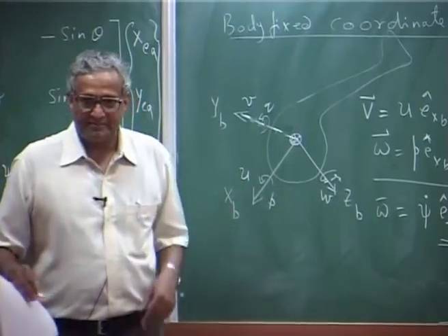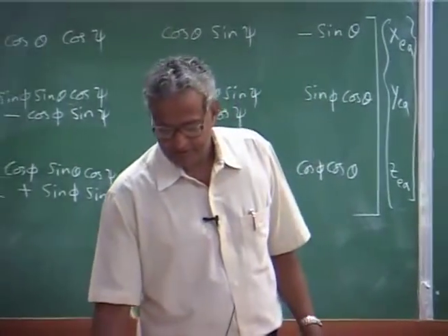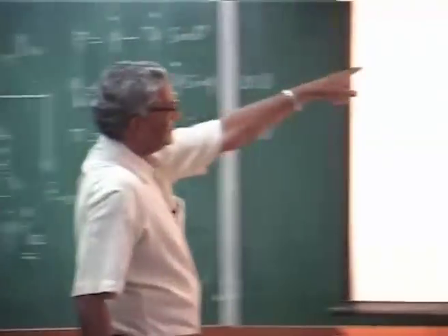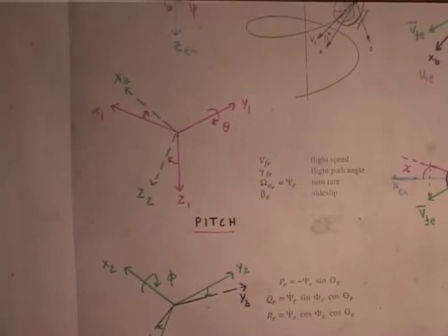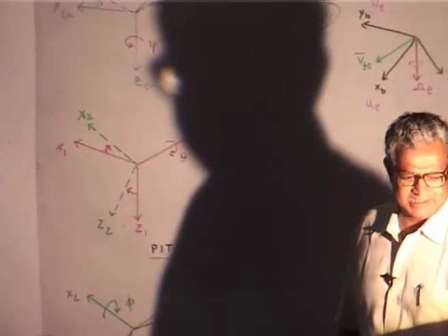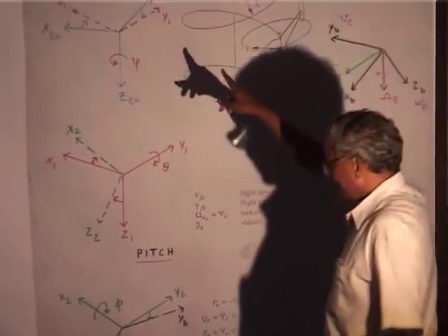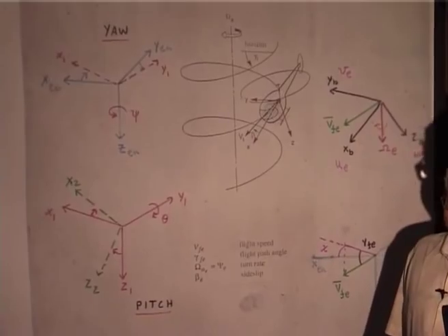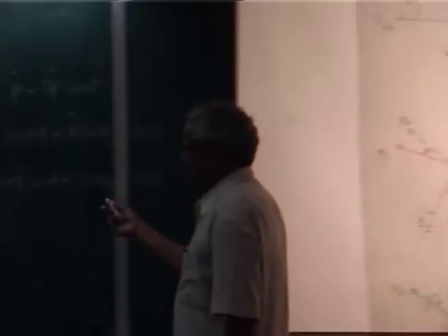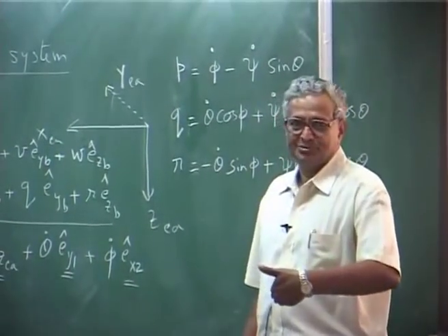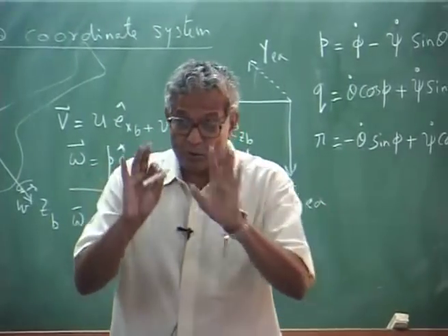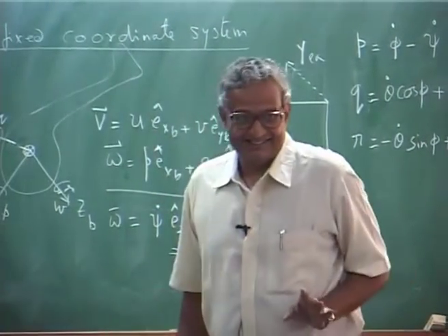Now, if I want, yeah. Again, like the theta, phi and psi. Yes. Now they are with respect to what point? As you have defined here. Okay. That is why that sequence, what sequence you follow, is the most important thing. This is the sequence we are following. Suppose if you change the sequence, you will find a different thing. Usually that is why I said yaw, pitch, roll sequence is followed, so that everybody understands the convention, and they try to use the same coordinate system also. Okay.